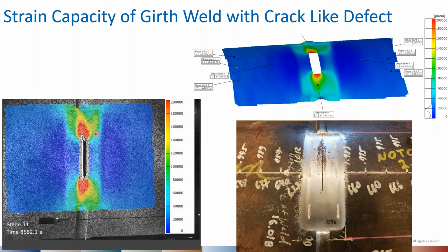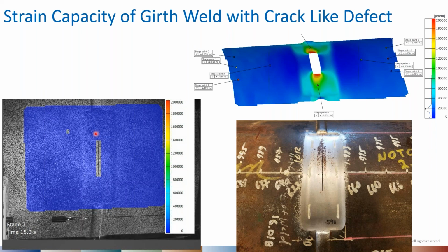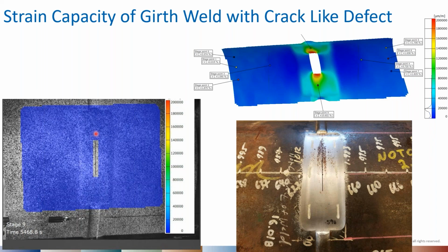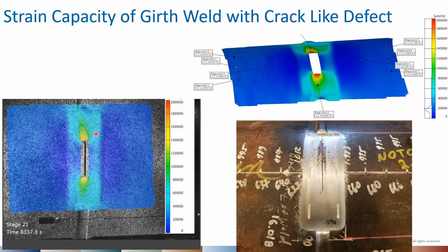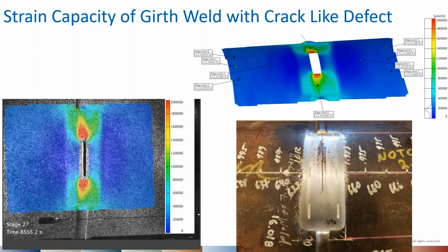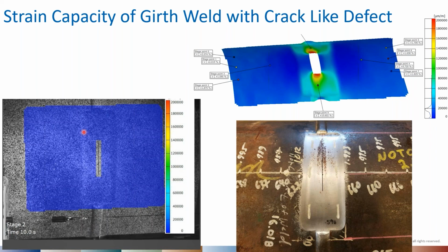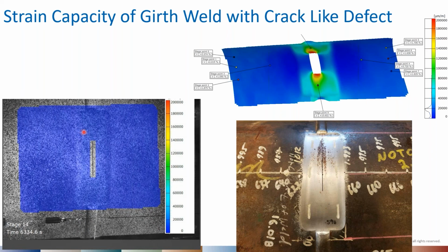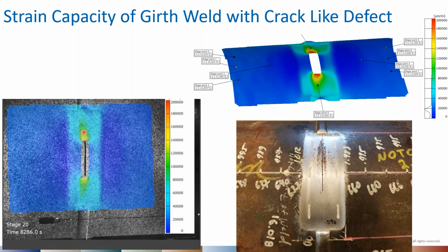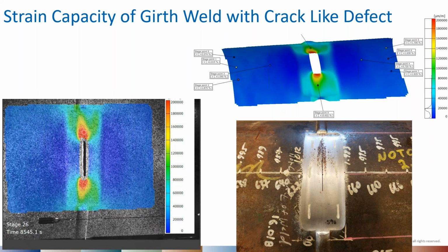One, because we get a lot of elongation of the sample because we're going all the way to failure, and there's a high stress gradient. So any strain gauge that we would put kind of in this area would only pick up an average underneath it. But with this DIC technique, we can get the full field strain and use that to update the finite element modeling predictions of this particular component.